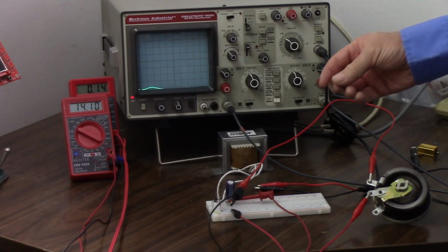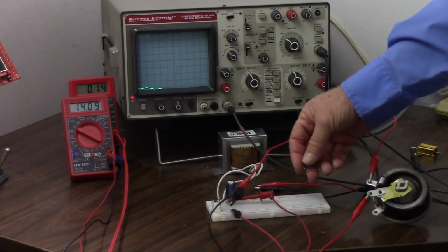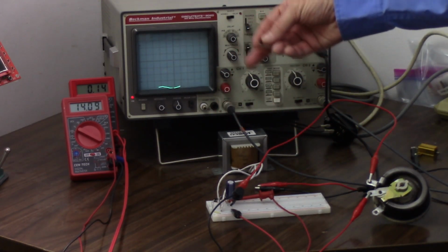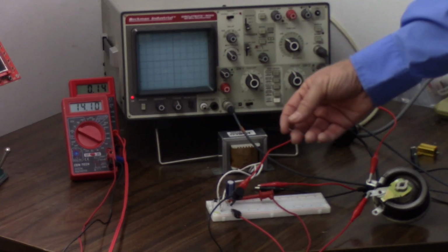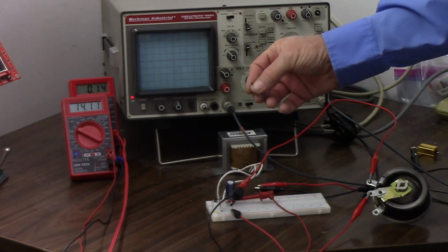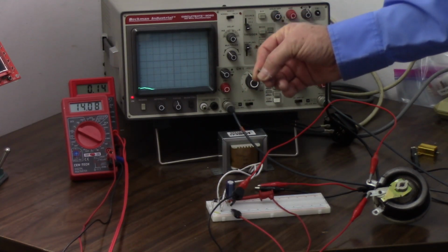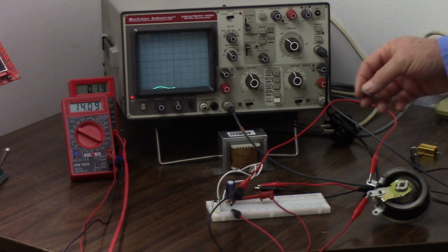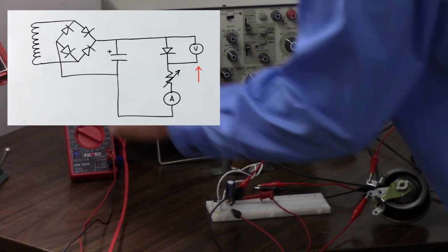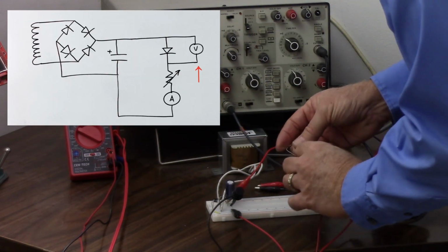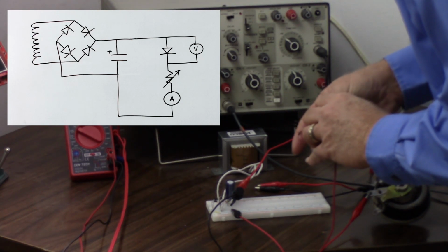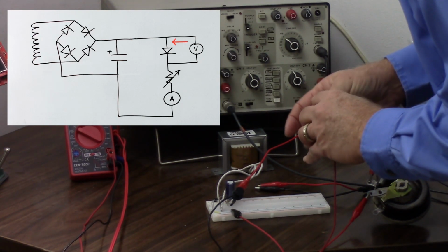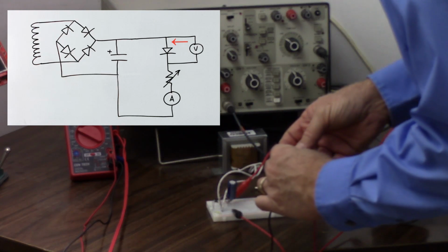Well, what we can do is put one of these diodes in series with the load and measure the voltage across it instead of the voltage output. We'll crank up the load until the current gets up to 500 milliamps and then see how much voltage we have across here. Should be 0.7 volts, right? Well, let's find out what we really get. So here's my voltmeter. That's this lead. I want to put that at the anode. Put the black lead at the cathode.